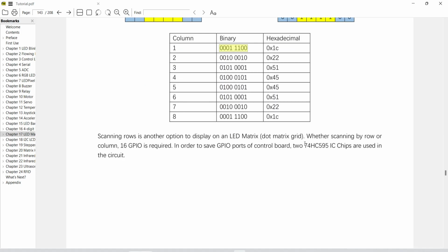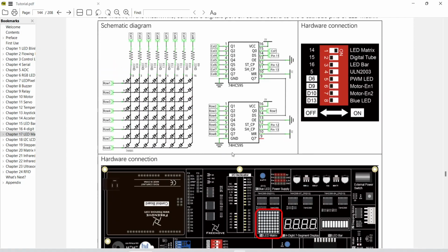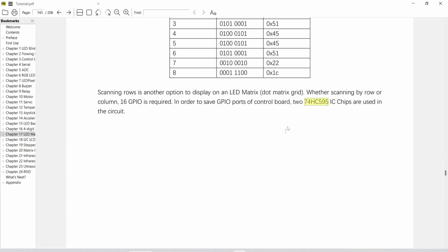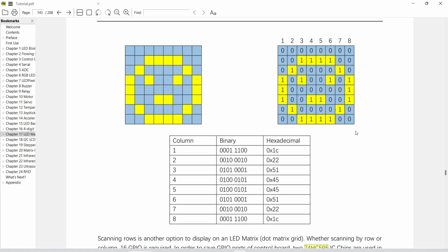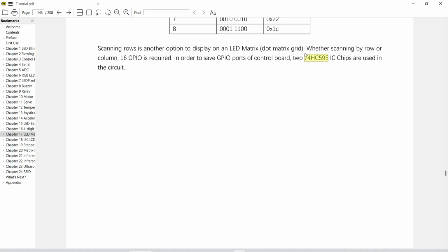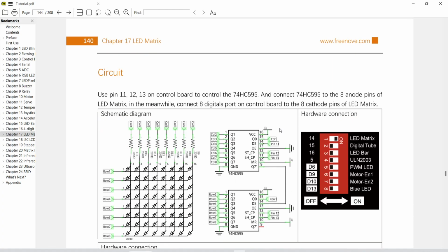Otherwise, we can just use this IC, and this IC will be handling all of that mess that we could have created with the pins for us. Okay, so what we do, we will just throw in a word. By word I mean this one, the 1 byte word. Each hexadecimal number is equivalent to 4 bits. So we put in the 1 byte word, and it will distribute that 1 byte into its corresponding pins.